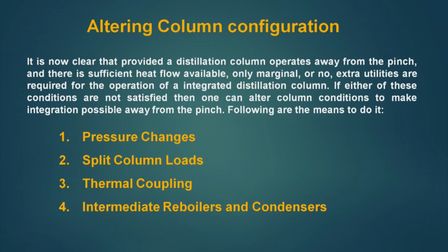Now, it is clear that provided a distillation column operates away from the pinch and there is sufficient heat flow available, only marginal or no extra utilities are required for the operation of an integrated distillation column.